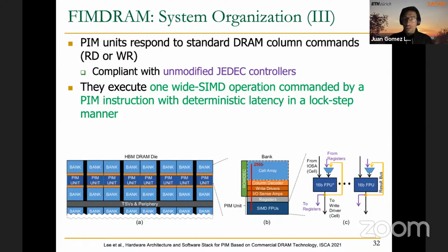So for the 16 data elements that we are operating on in the 16 different lanes, we make progress at the same time. That's why we talk about lockstep execution. If we go back to the idea of GPUs I mentioned, I think that warps are also executed in lockstep.